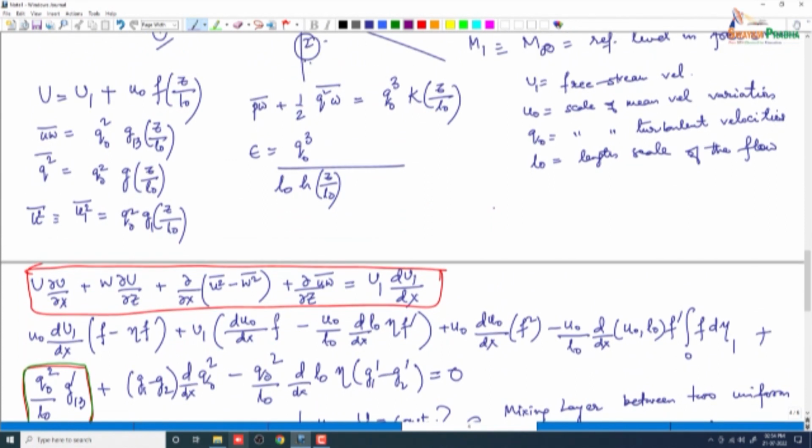Now, the Reynolds stress takes time to develop and decay, and depends on the rates of spread and the conditions upstream. These are a few pointers to a more realistic picture, compared to the distribution we have taken here.